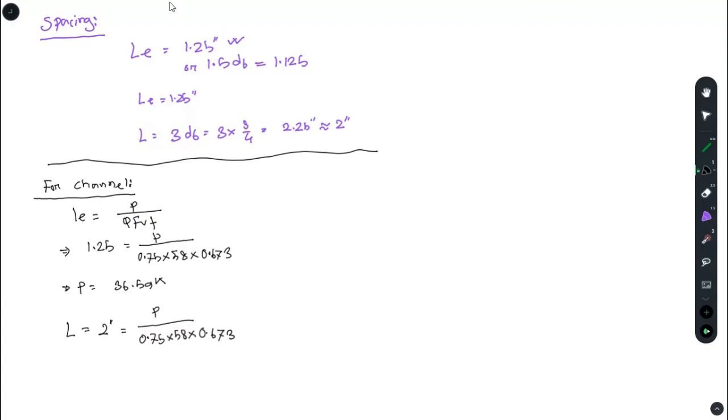But here there is one extra thing, that is this L value, which is in between spacing, has another parameter, that is half dn, and by dn we mean the bolt diameter, which is 3 by 4, plus the clearance, which is in this case, let's say 1 by 16. It is assumed. From here you'll get a P value of 46.66.